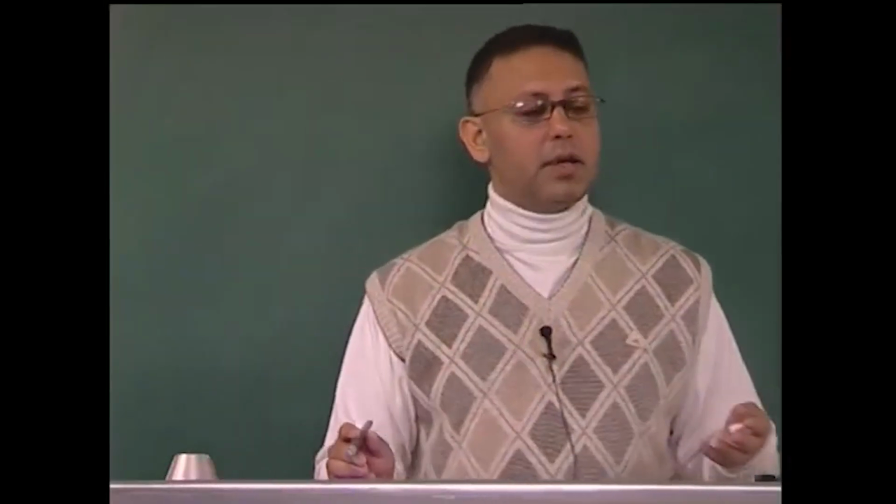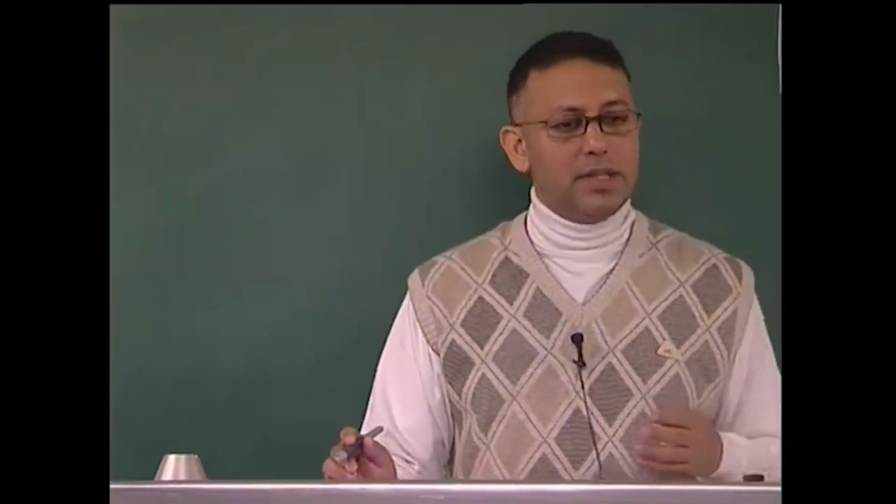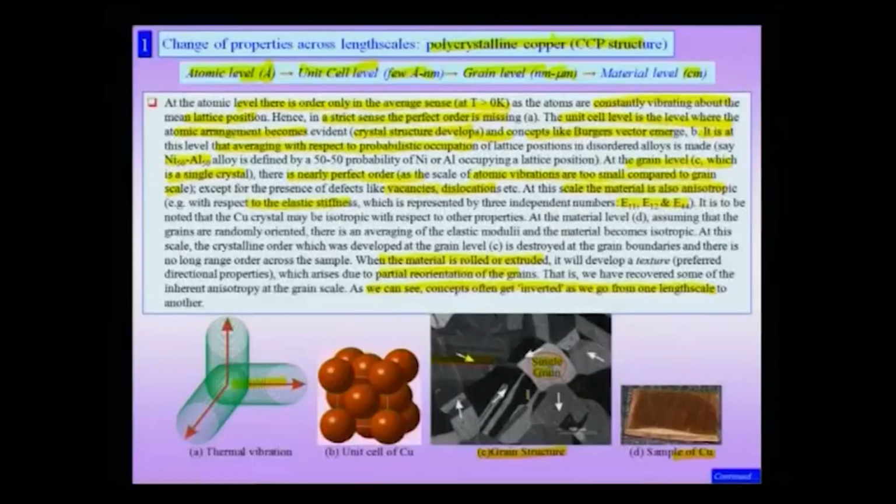So, a material typically with randomly oriented grains is completely isotropic, and at this length scale, I do have to worry to some amount about the crystallographic defects present in the material, but more importantly I also have to worry about the defects which arise between the grains. For instance, now I need to worry about the grain boundary in the material. So, as I am going to different length scales, I worry about different issues which finally affect my properties.